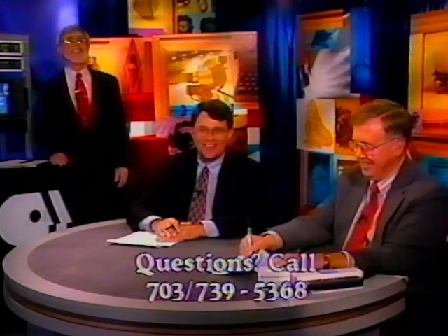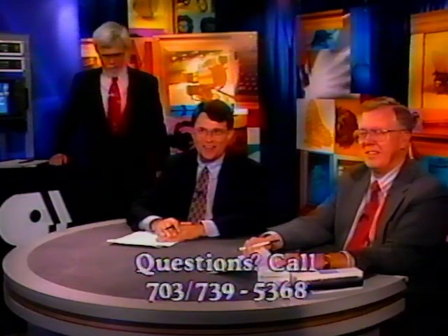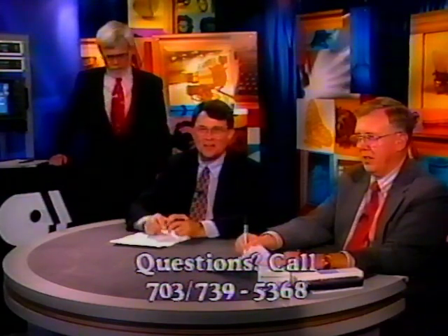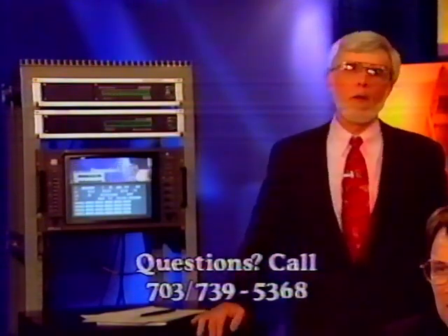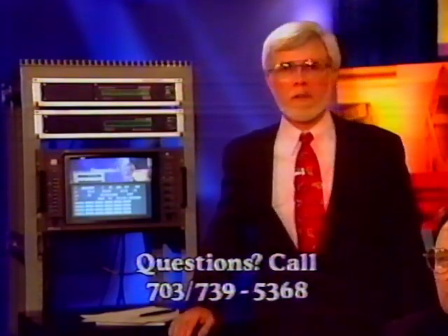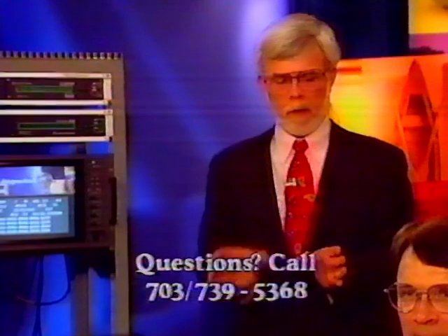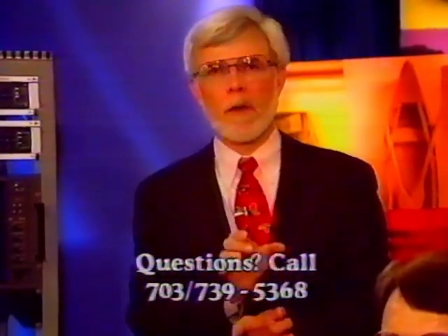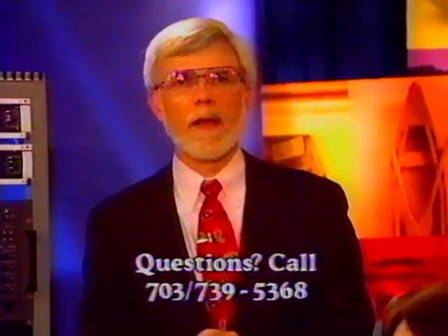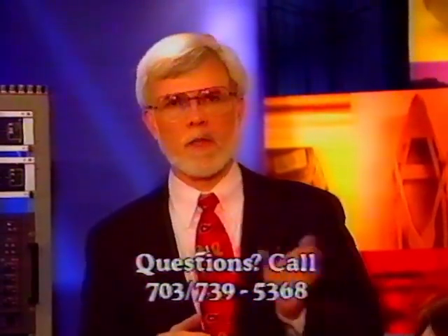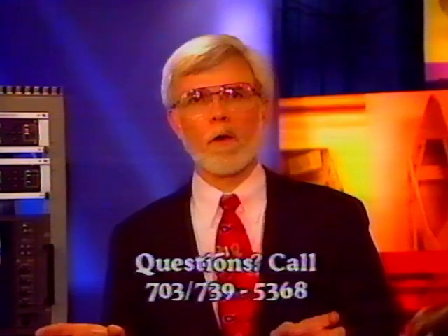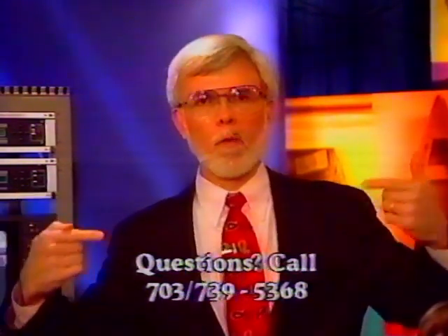But anyway, I've got a couple of questions for you. The first one is, what exactly do the FEC numbers mean? I know FEC means forward error correction, but what does 3/4 mean, for instance? Well, that's 3/4 forward error correction, and that is the amount of bit overhead that is devoted in the data stream to actually verifying the bits that are present in the data stream. There's a whole series of symbol rates and forward error correction rates that work in pairs.